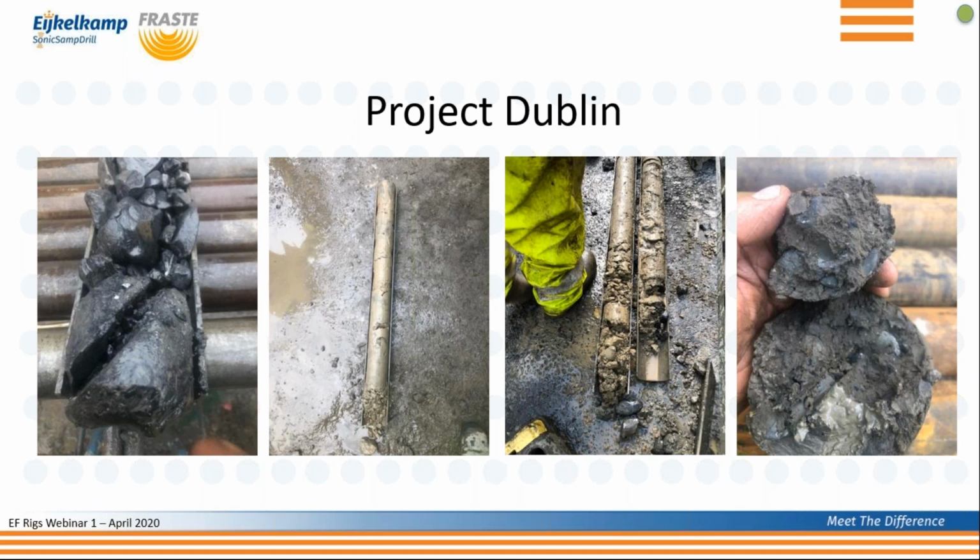A bit further along on the project, they were using cable percussive, and they were having to drill in sort of a 10-inch diameter casing and drop down because of the boulders, and they'd spend a week chiseling away, smashing the boulders to pieces and shelling them out and putting them in buckets. Now, they know they're on something hard, they know they're on something big, but they're never going to get it out to look at it properly as to what it is. They've got to smash it to get it out. So again, this was a problem.